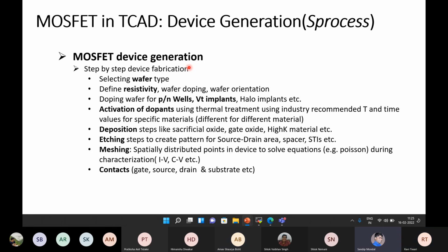Okay, Arnab, to answer your question in depth, take meshing for example. Let's say you have a large square area, and you want to divide it into several small squares, so that you can solve your mathematical equations within these small square boxes. If your mesh is very small, the accuracy of your calculation is more proper.